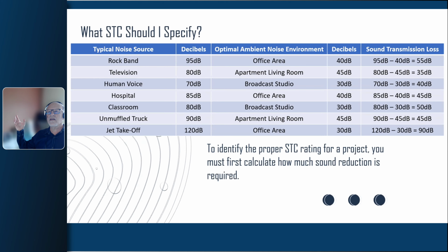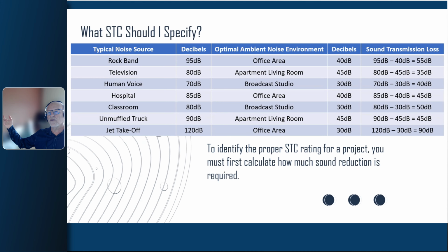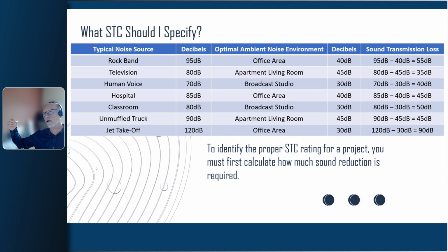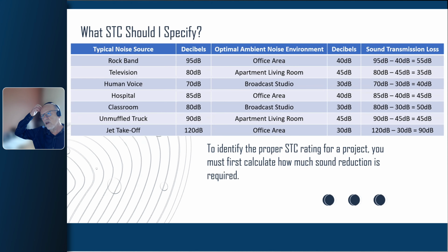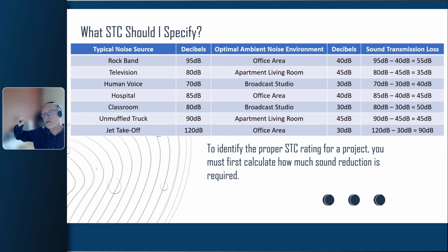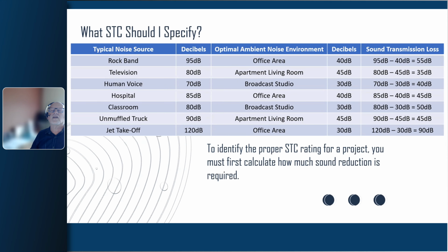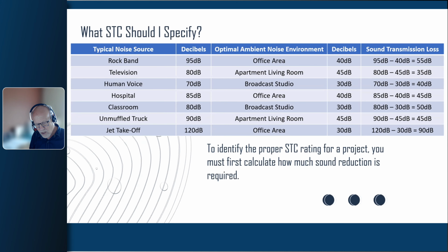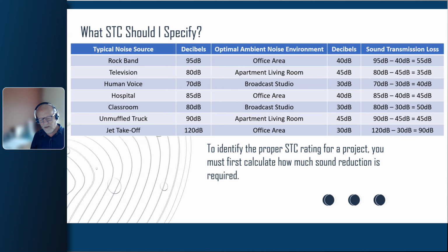The test was to create noise in the stairwells and outside rooms and make sure that we were achieving the STC 50 rating inside the exhibition hall. And so we did that test on 6 different openings, and it was successful. We achieved more or less STC 52.